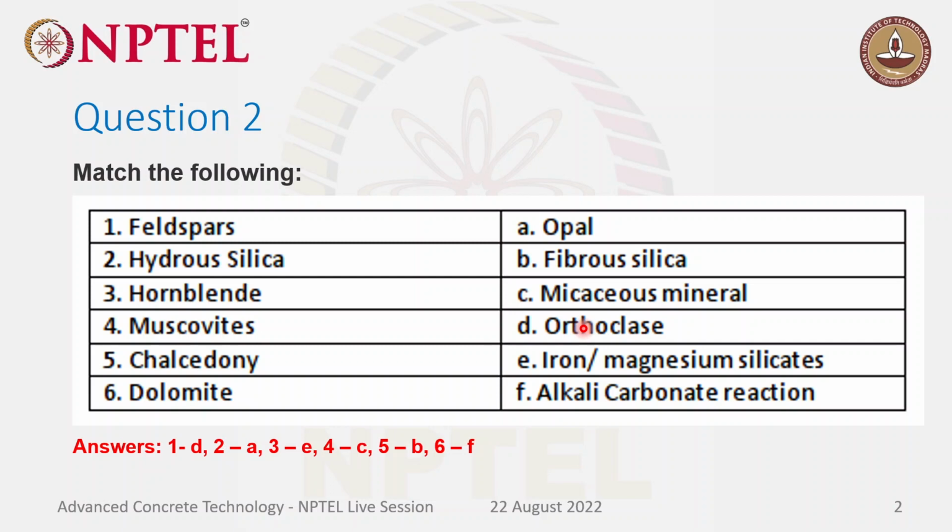Okay, ma'am. And how about these other elements, like, ma'am, at that time the sand will also be there. Then C3A, C3AF will also be there, some of these components. Sorry, C3A, what is that? Ma'am, tricalcium aluminate. If some elements are left out, ma'am, they might not have participated in the hydration. Just think about the fraction left unreacted. How much will be there? It will be very less, ma'am. Very less, yeah. But again, if those elements are combining with the new hydration process, will it affect or not, ma'am? That's my query.